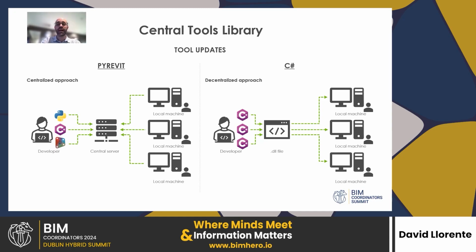The tool updates are easier in PyRevit as well. When we were using C#, once you have all your scripts or your add-in, you need to create a DLL file, and this DLL file needs to be installed in every local machine. That's why we were having problems when we were doing updates.